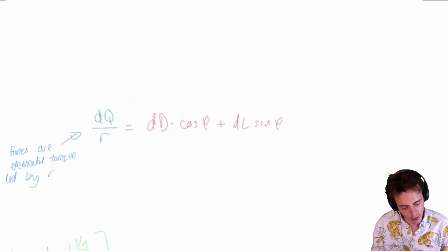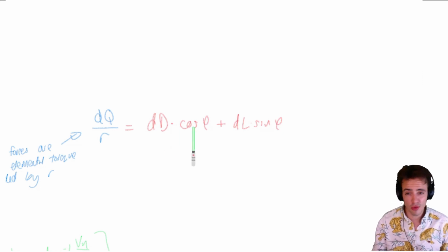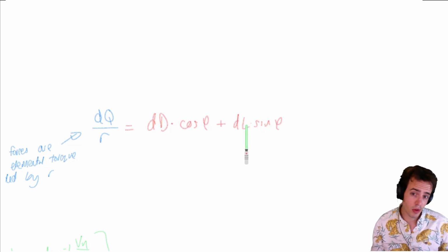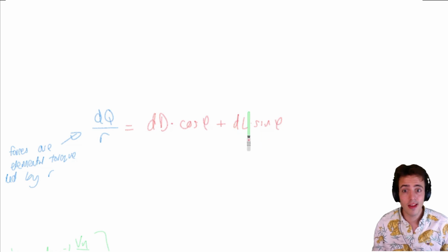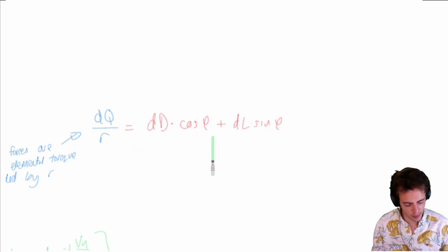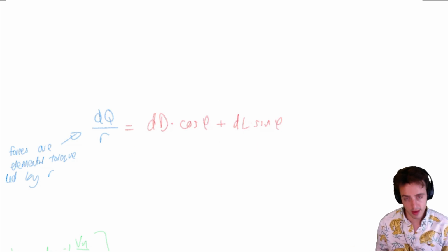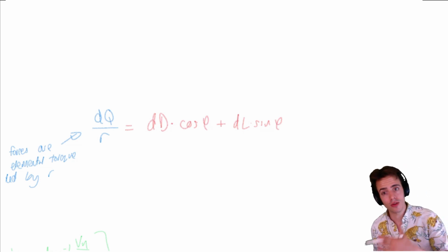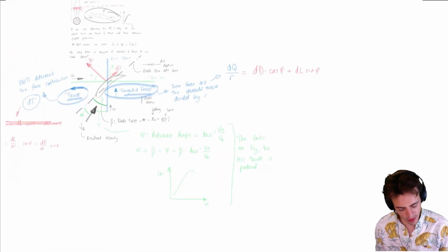If we look at the torque, the thing that makes the blade difficult to turn, then again, our drag is the chief contributor towards making the blade difficult to turn. But we can also see that if we produce lift, which is what helps us produce thrust, the blade gets more difficult to turn as well, and not just as a consequence of the drag that's being produced. So these will help us understand a little bit later how our power and torque requirements change with propeller performance.